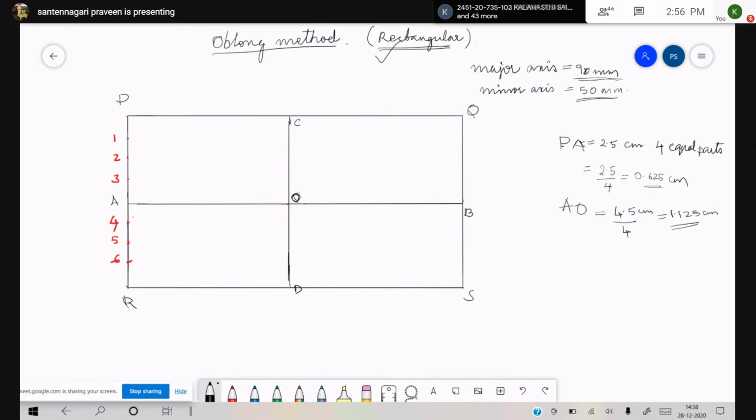See, one important thing with common sense you have to think is, here we got these points in decimals, 3 decimal, 4 decimal, sometimes 2 decimal. So you cannot divide your line because the normal centimeter scale that you are using generally has millimeters and centimeters, with which you cannot divide 0.3 decimals or 0.4 decimals. So when it becomes difficult, then you take the option of dividing the line by the method which I have shown you earlier.